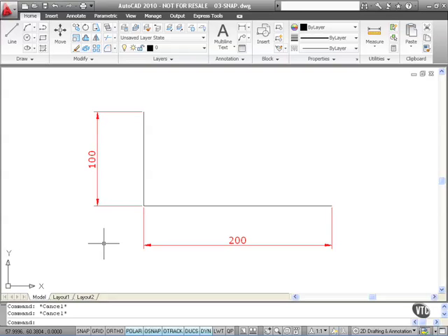The 200 long line will have 20 increments of 10. I can snap to those increments very easily. The one thing I do know here, which is a little bit of a cheat actually, is that where those two lines intersect is the coordinate 100, 100. So they're all placed exactly on nice, neat coordinates.